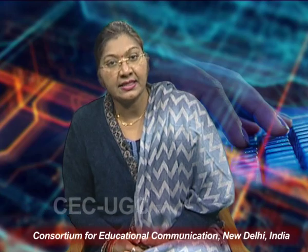In some cases, a crystal possesses a unique polar axis even in the unstrained condition. This can result in a change of the electric charge due to a uniform change of temperature, and this is called the pyroelectric effect. The direct piezoelectric effect is the basis for force, pressure, vibration and acceleration sensing, and the converse effect is used for actuators and displacement devices.